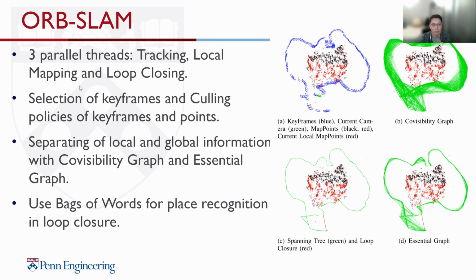out tracking, map building, and loop closure. So it uses a different algorithm for loop closure and for tracking. We know tracking is ORB SLAM, because they use the ORB feature extractor. For tracking, you have two frames, then you do feature extraction and find the feature matching, right? And you save it into the whole map you have. Then you find another frame and do the feature matching again.